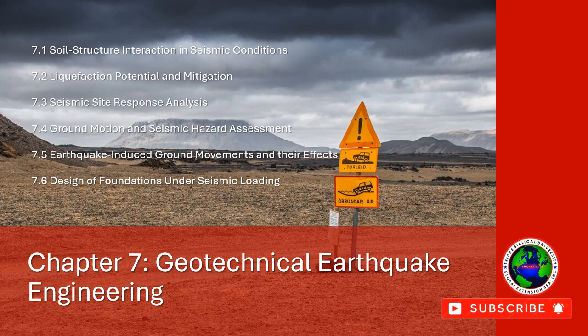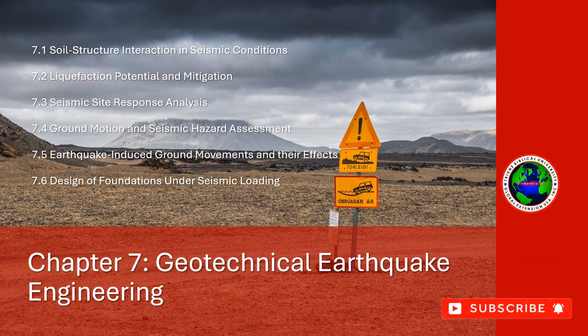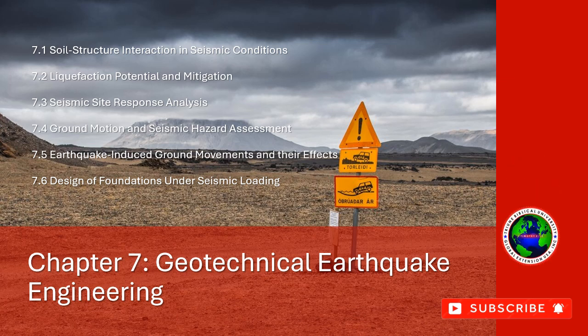3. Frequency dependence. The frequency content of the seismic waves is important when assessing site response. For example, soil layers may amplify lower frequencies more than higher frequencies, which can have a greater impact on structures designed with specific resonant frequencies.